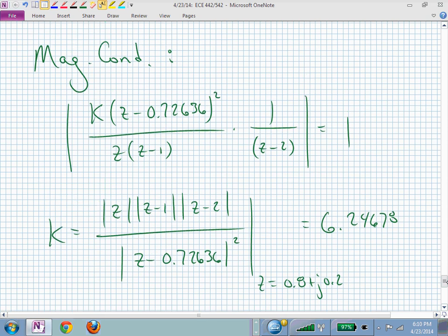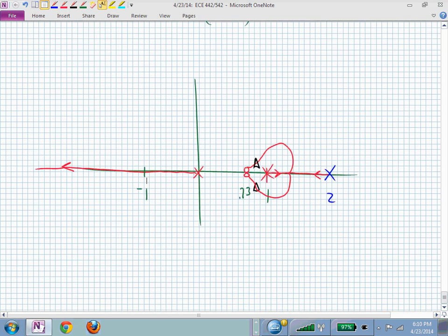We have this nice formula for k, don't we? How can we use that to check whether or not the third triangle is inside or outside the unit circle? We plug in z equal to -1 into this gain, and then what are we hoping? You hope that gain is greater than 6.25, right? And then your triangle would be inside the unit circle. So we're trying to find what's the gain to get us there.